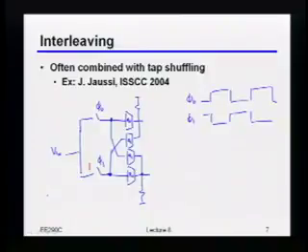Yeah. So why are these architectures being developed on the receiver end? Okay. So there are multiple different reasons. In the high-speed link context, as I mentioned, it generally is not used that often. But there are other contexts where it makes a lot more sense. To give you an example, I can't always necessarily talk to my own transmitter, right? So if I need some sort of feed-forward equalization, which I'm going to need if I have any significant precursors in my channel, then my only choice really is to build it on the receiver. Because if I can't tell my transmitter to do it, then I'm stuck. I just have to do it at the receiver, right?